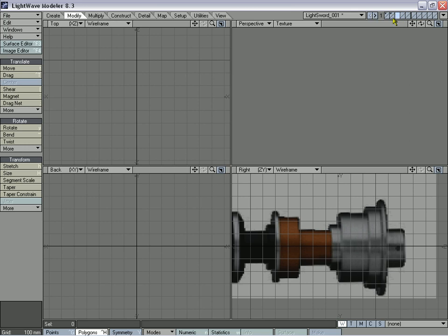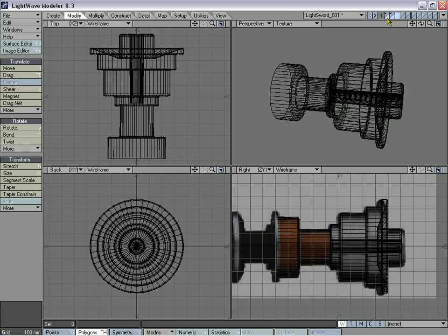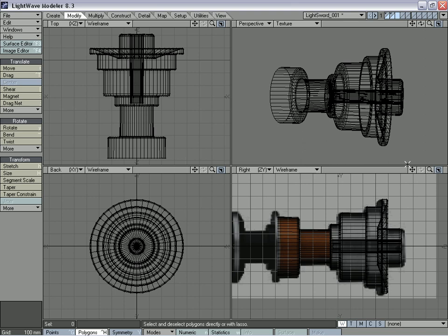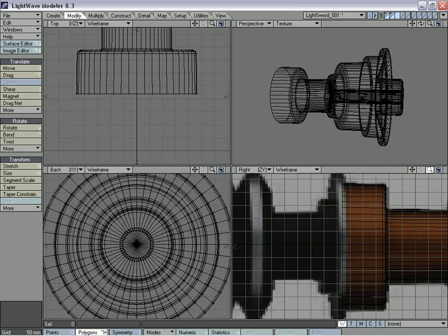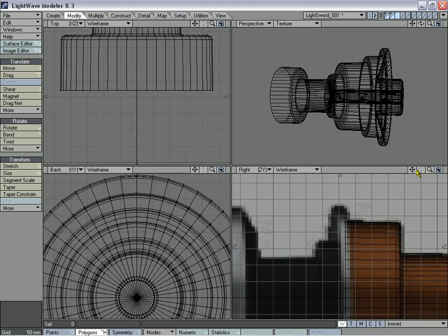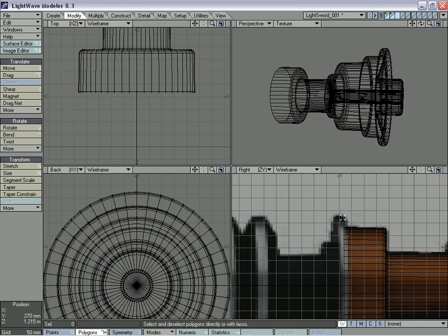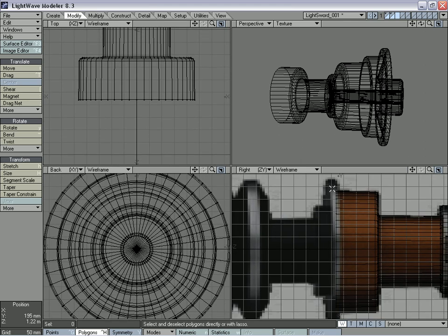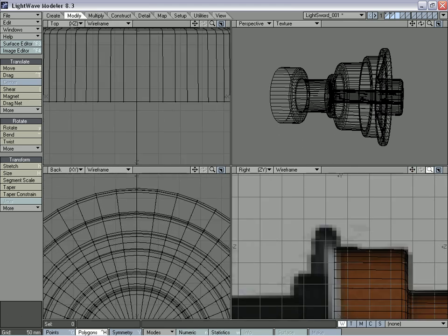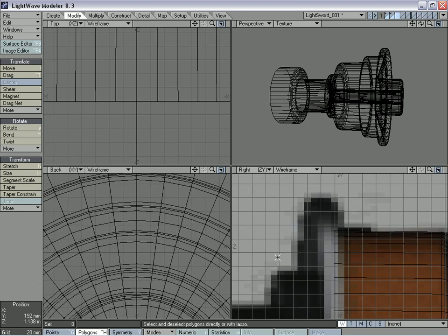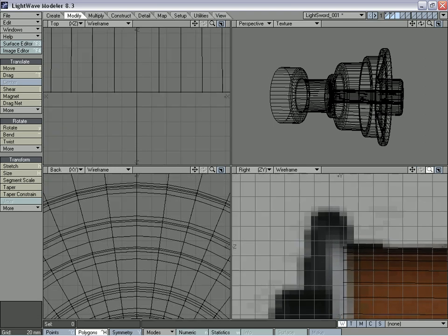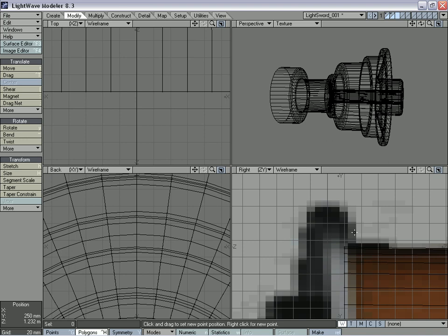So we open a new layer, hold down Shift, and click these tabs underneath, put them in the background layer. And now we're going to create just this ring right here. Just this small silver ring, because the next section is black. Alright, so Shift and the plus key to create our points, and create 3 of them, and align them how we want them.